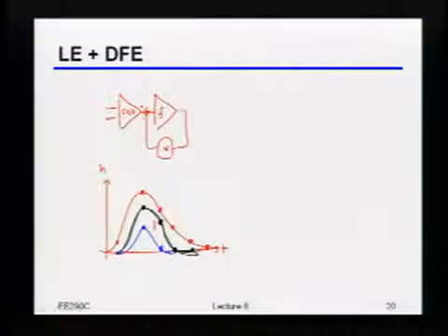Okay. So indeed, because you always have to throw away DC gain to get a certain amount of peaking, that means you'll actually get a larger signal swing by backing off like this. Okay? So when you really do combine these two things, that means you want to set things based upon knowing how many DFE taps you're going to be using. You also want to build your linear equalizer keeping that in mind. Okay? And so I'll just mention this briefly.